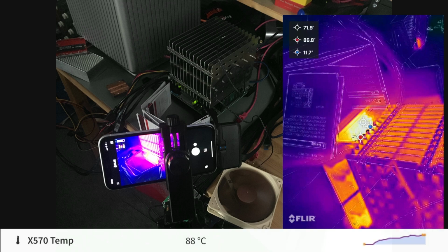When reading over IPMI, we observe we have 88 degrees. When reading the temperatures of the heatsink over the FLIR camera, we see that we are somewhere between 85 and 87 degrees. So the order of magnitude is correct. However, we cannot make assumptions on the temperature difference between the die and the heatsink because of the uncertainties with the measurement on the FLIR camera.